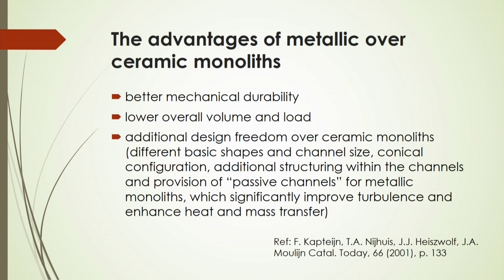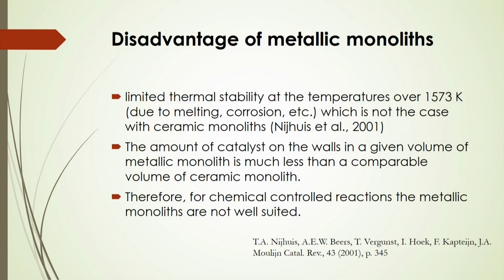You will also see that metallic monoliths have better mechanical durability, lower overall volume and load, and additional design freedom over ceramic monoliths. There may be additional structuring of the channels, and provision of passive channels for metallic monoliths. That may significantly improve turbulence and enhance heat and mass transfer in the case of metallic over ceramic monoliths.